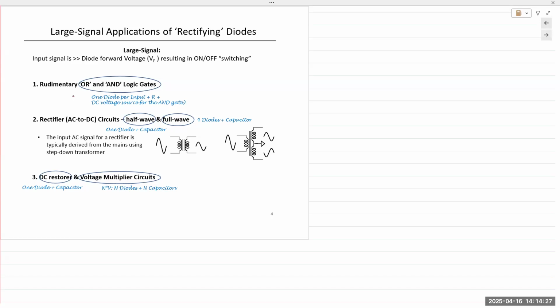So one of the most common applications for a diode is in rectifier circuits, where we convert AC to DC. It's the most common circuit or application for a diode. It's present in every single electronic device that can connect to an AC outlet. So your laptop chargers, adapters, monitors, projectors, cameras, everything that is powered from a wall outlet from AC is always converted into DC. So there's a power supply that is built into all of these electronic devices. Inside this monitor, inside the computer, the monitors that are on the wall, everything has a rectifier circuit inside it.